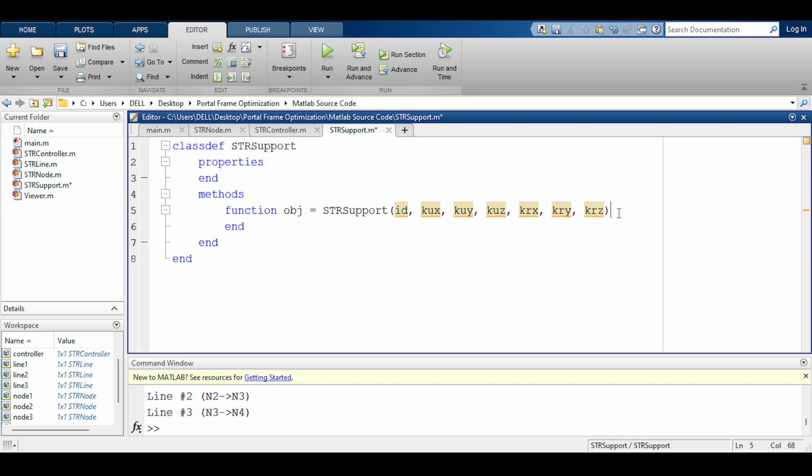You see, the way I am going to model supports is not simply the dashing things from MATLAB. It's not going to be simply the static condensation where we remove rows and columns. No, I'm going to allow the user to provide an elastic support if he wants. An elastic support can be used to mimic, for example, raft foundations or beams on elastic soil. Now, what about a normal pin or normal fixed support? If you want to define a normal fixed support, then this would cause the stiffnesses to go to almost infinity. And if you want to define a pin support, then the stiffnesses go almost back to zero for the rotation.